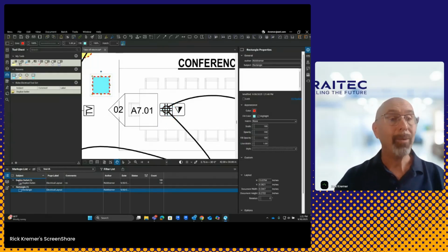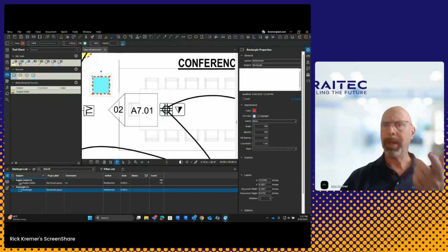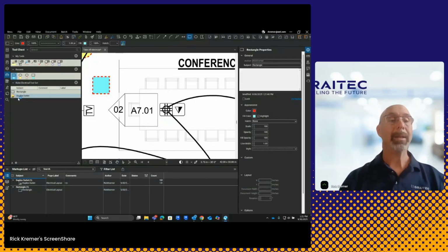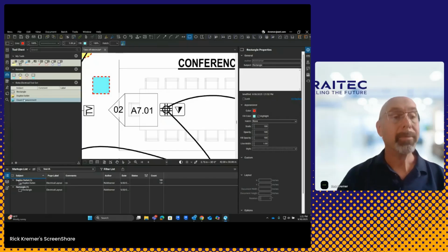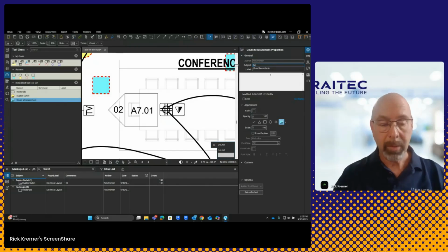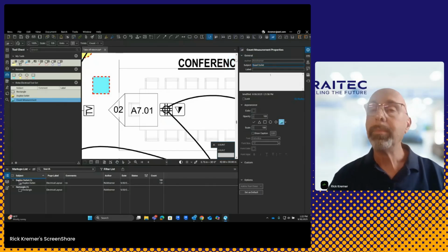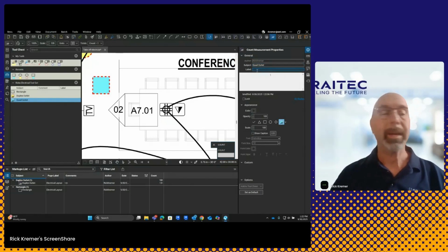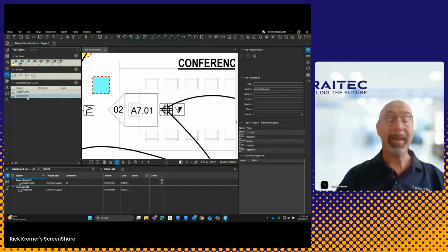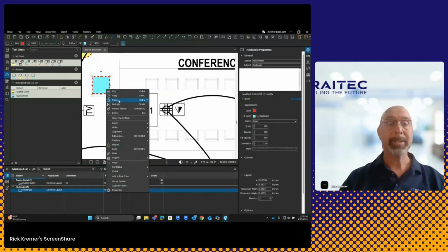Remember, it's now right here in recents. Let's give that a counting object. So I'm going to left click on it and simply drag it into my electrical tool set. Right click on it and create count. Just like before, I'm going to select it. Over here, change this to quad outlet and tab into the next one. Perfect. See how easy that was? And I'm going to delete this. Next, let's find how many quads we have. Let's delete this.